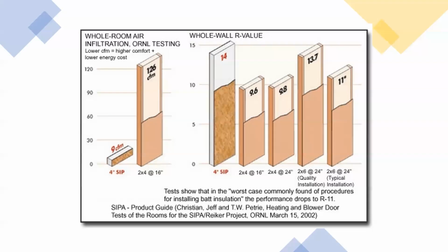That's why grading is also key, because not only do you have a 2x4 wall with R15 batt performing at a 9.6, now you grade it as a grade 2, it's going to drop that 9.6 even further. And then, of course, you punch holes in the wall and call it windows and doors, and now you have a problem with that as well. Yes, Cody, you're right. Compression also affects the R value. Absolutely. Thanks for joining, Cody.